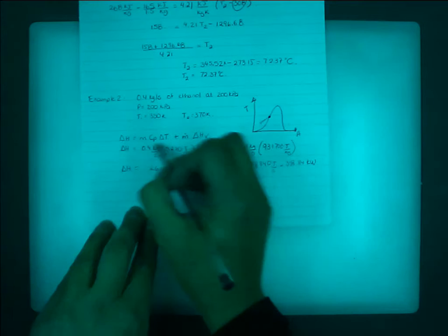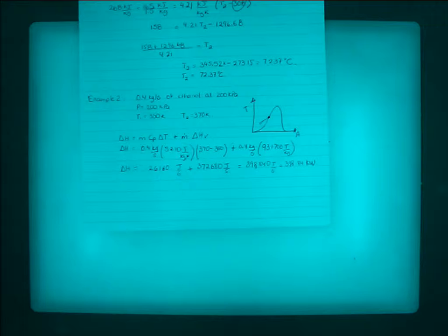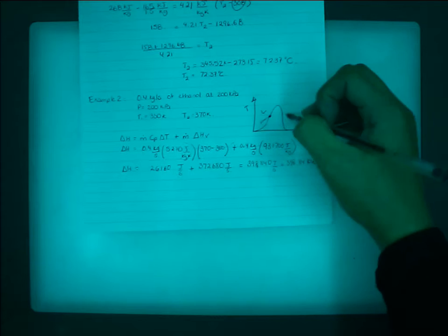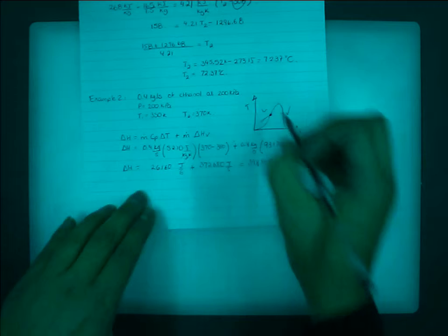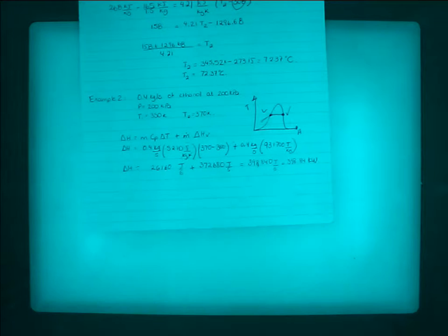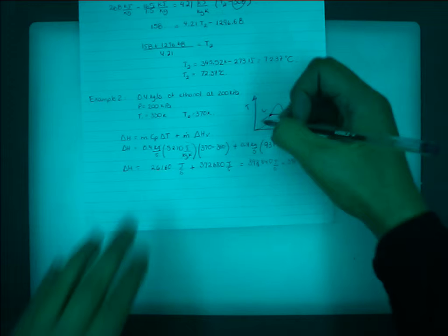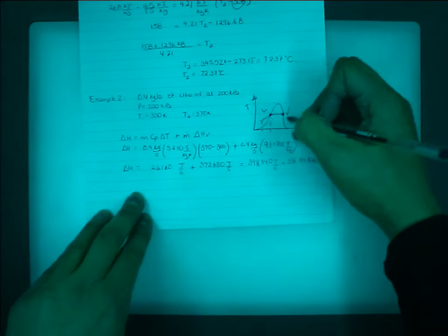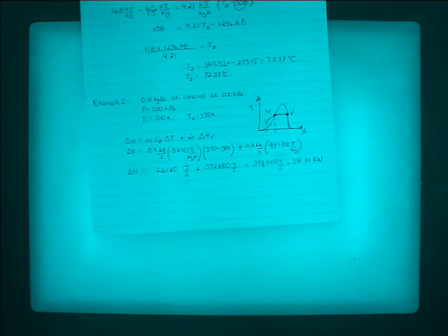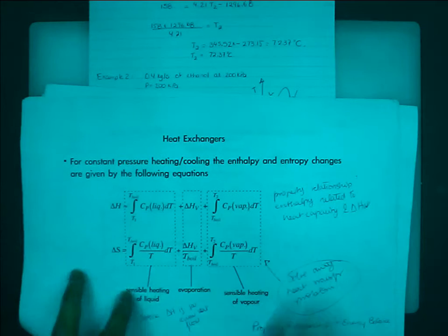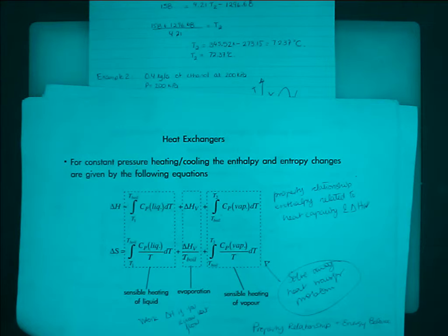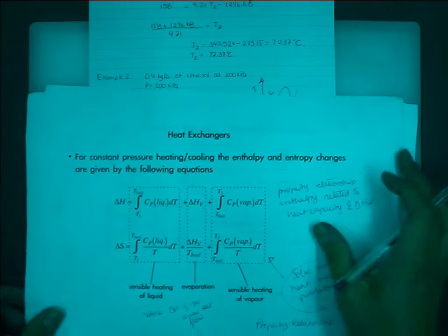The equation that I'm referring to is the equation we just saw, very similar to the equation that we used when we were looking at enthalpy. Okay, so if you understood the first lecture, then you should be able to catch up on this part. Now, we go from T1 to T-boil, so 350 to 370. We then add the heat to make the phase change, and that's it, we stop there. So this part will be essentially zero. Imagine that as an engineer, somebody is telling you, please, I just want to supply my plant with water vapor. I just want vapor into my plant. So the only energy that you will provide is to produce the vapor, and that's it.